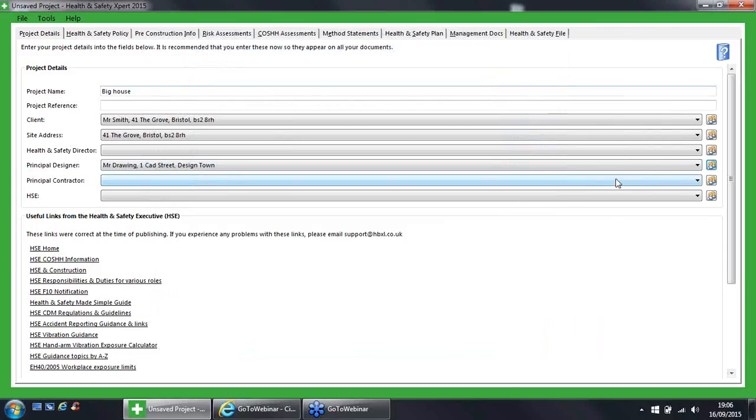The next thing we need to have is a principal contractor. Now, there's a good chance that this could be you, or it could be someone that you have working for you if you have someone who is subcontracting and they're going to take over the role of principal contractor. Under Health and Safety 2015, the principal designer is responsible for the health and safety during all the pre-construction period. Once you break ground, so to speak, depending on who appoints who, your principal designer may maintain control of the health and safety through the project.